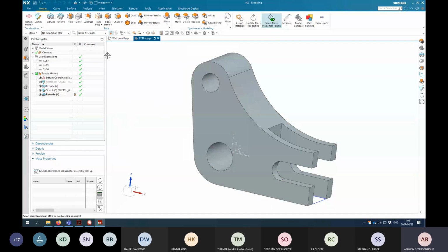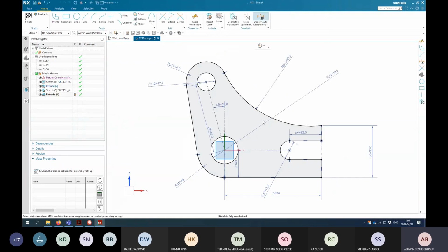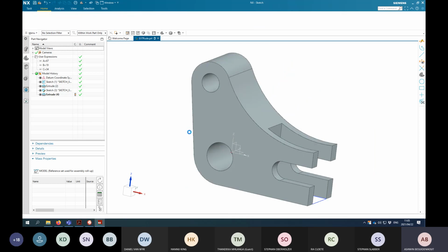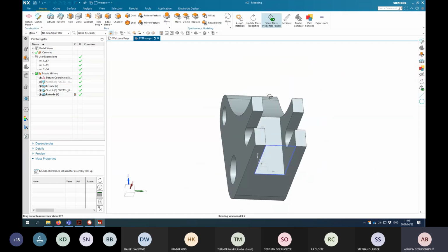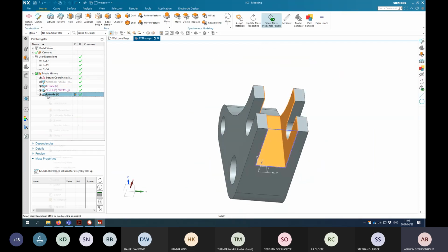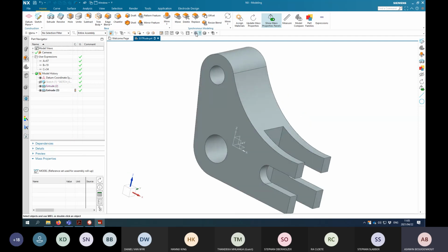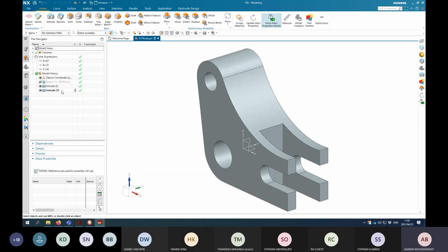So now I know if for some reason the designer thinks that this must be cut, this value should change, that cutout won't be affected, because it doesn't matter what this will be, it will always go through all. Okay, so that's fine, right? Let me make this sketch internal. I'm not going to use it anymore, so just clean up my tree a bit. You don't need to do that. You can leave the sketch, personal preferences and so on.